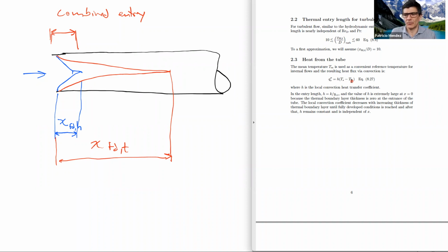It's a subtlety. The formula looks so much the same, but this is not a maximum temperature, not free flow, because there's no such free flow either. This is the mean, the average temperature. And the average temperature is what we have been using all the time without explaining it too much when we talked about advection in pipes. We would calculate heat fluxes based on temperature differences without ever saying that the temperature actually had gradients. In reality, those were average temperatures, mean temperatures. That is what is indicated here. Important to keep in mind.